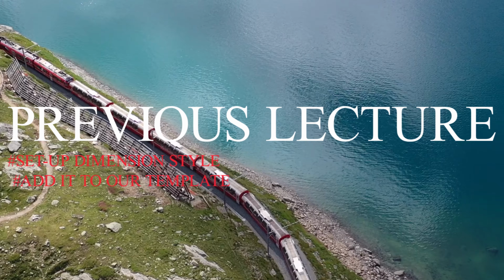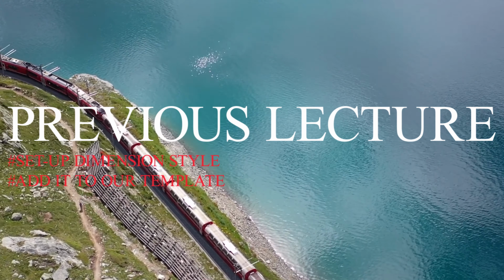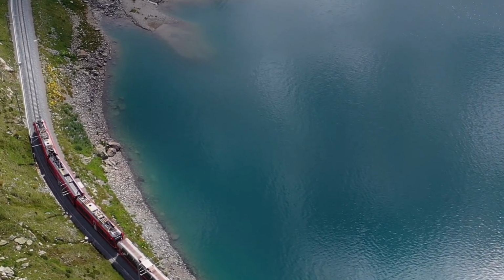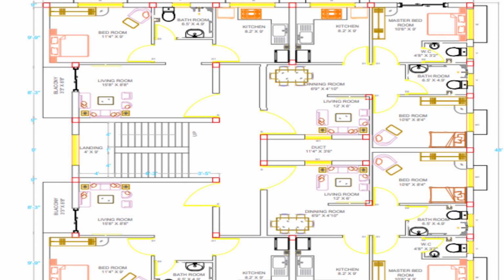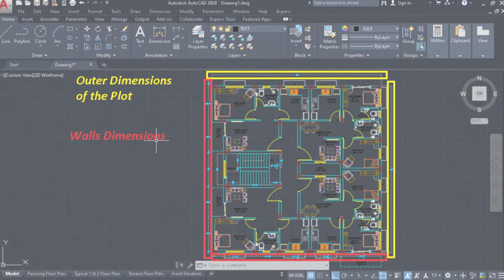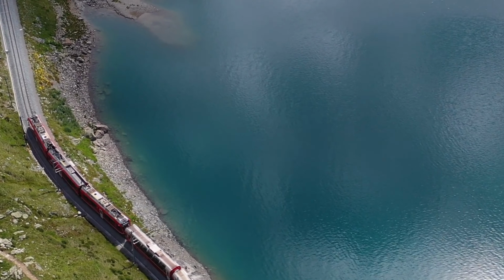In the previous lecture we have learned how to set up our own dimension style. We also added it to our template setting. In this lecture we will form our own text style, so let's get started. As we said before, in architectural plans dimensioning is done in two steps. The first step, the outer dimensions of the plot and walls dimension. In the second step, the inner room names and dimensions are denoted with the help of text tool. So let's move on to form our own text style.